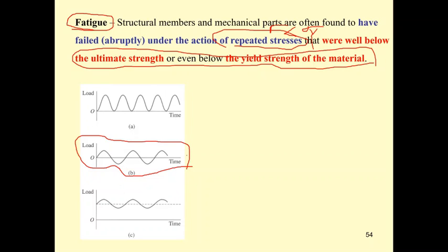When we do the fatigue test, we put a round specimen and bend it. When we bend it, the bottom is in tension and the top is in compression, and then the motor rotates the specimen, so the part in compression starts to be in tension, and the part in tension goes into compression. So if there is a crack on the tension side, it is going to close, open, close, open, close, open, and it is going to get larger.